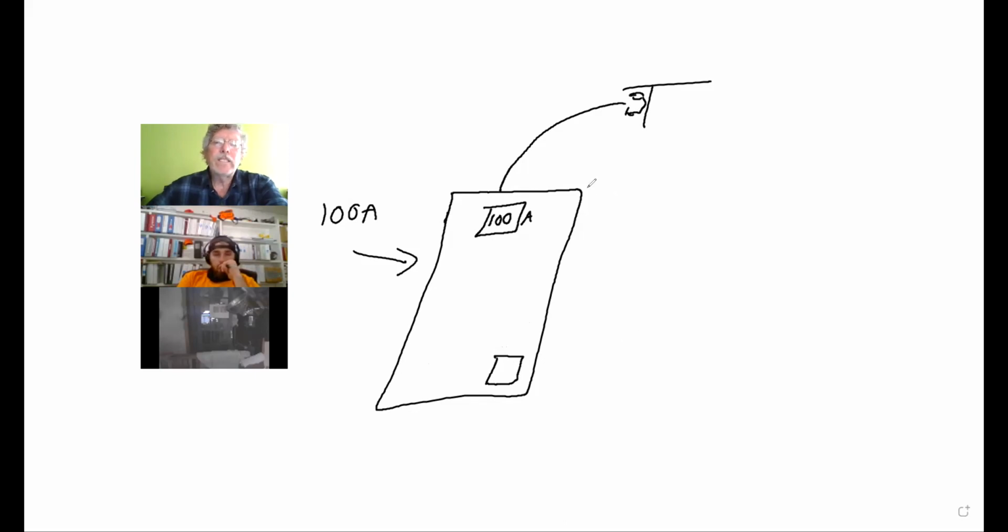And so what the question is asking is if you have a 100 amp service and the panel is rated for 100 amps, how much can you bring in? Well, the National Electrical Code, you could look at this and say, okay, we've met our rating, so I can't put solar in here. But the NEC says, you know what, you almost never use all the amps. So we're going to let you go to 120% of whatever the rating is. So that's telling me I can come in with a 20 amp breaker from my inverter.